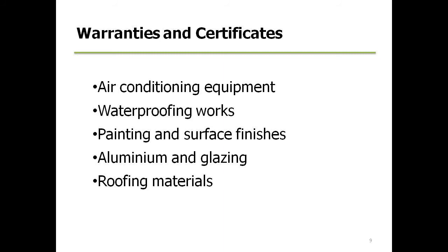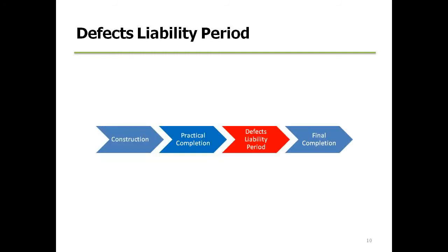So the defects liability period is usually 12 months, and in that 12-month period, any defects and faults that are identified in the building or the services are to be completed and rectified by the builder. As I mentioned earlier, it's that period where commissioning of all the building services and the hard structure in the building is done, and it can be further fine-tuned so it actually performs the way it was intended in its original design.